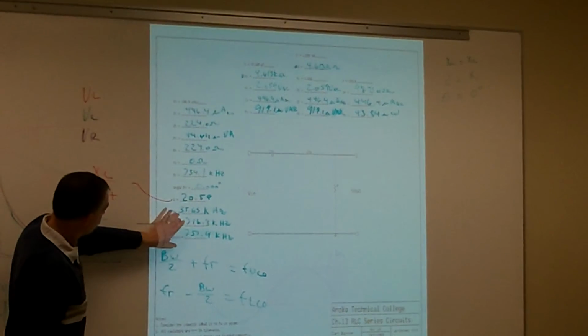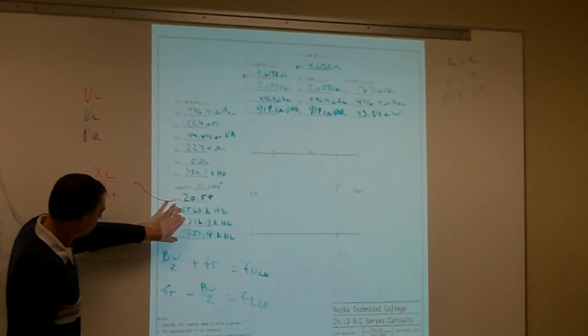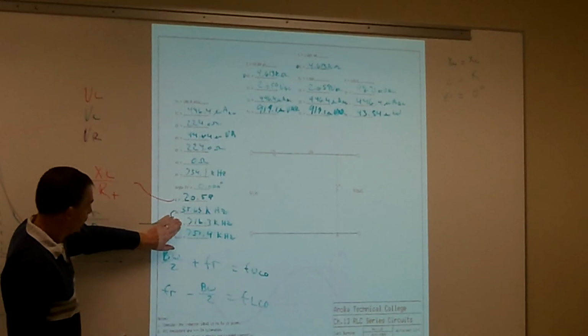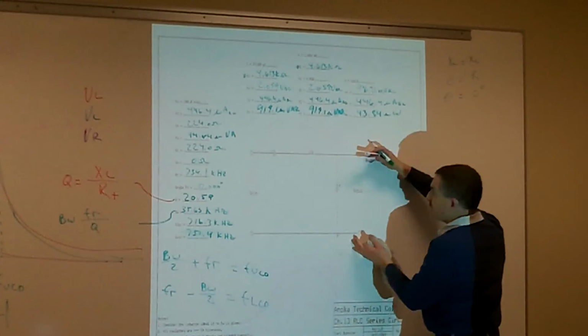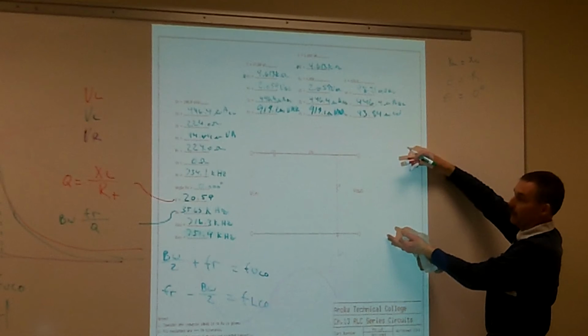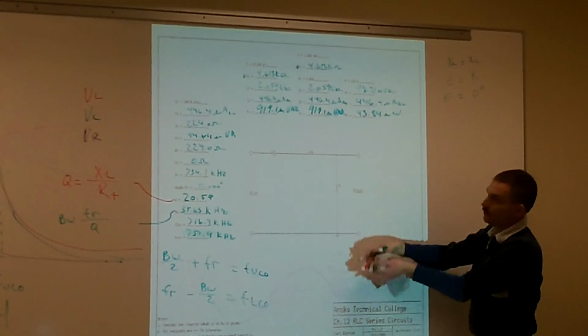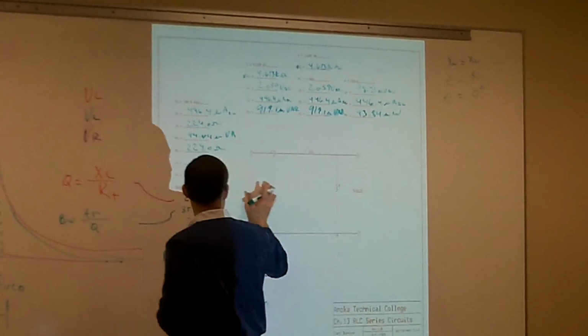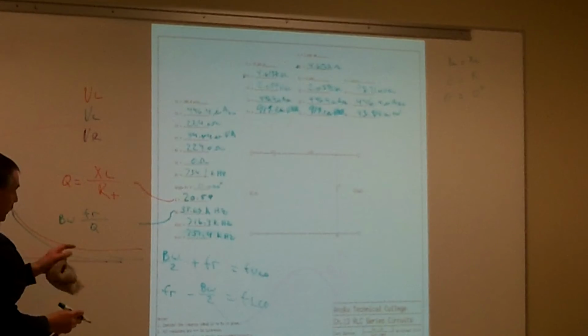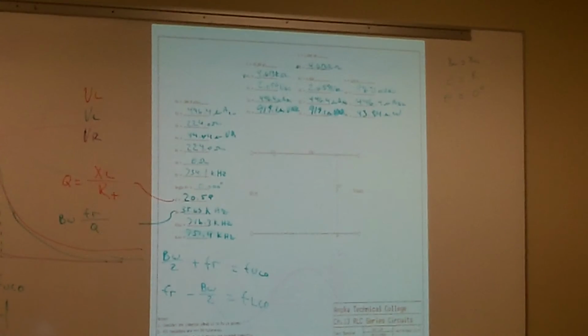And we come up with a quality of our circuit that depends on what our bandwidth is. For this particular circuit, the only thing that goes into our next stage is anything greater than 716.3 kilohertz but less than 751.9 kilohertz. Everything else is going to be rejected. Even though all these other frequencies are bombarding our circuit, those are the only frequencies it allows to pass on to our next stage, where we go into an amplifier stage and start amplifying. So this is our bandwidth, and these are going to be our frequency cutoffs.